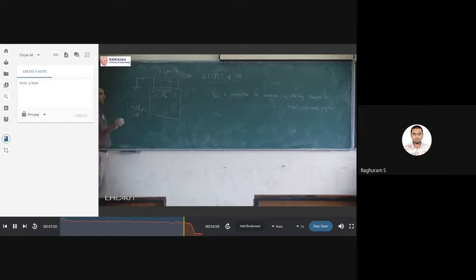So just by making the transistor on, we cannot say that current is there. Current will only come when I have a non-zero value for VDS. If VDS equal to 0, then definitely current cannot flow. That is the second thing to remember. IDS somehow has to depend on drain source voltage. If there is no voltage between drain and source, there will be no horizontal movement because they are at equal potential on both sides.